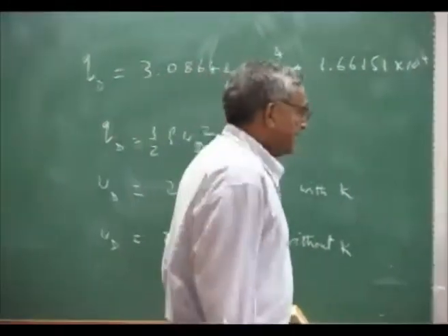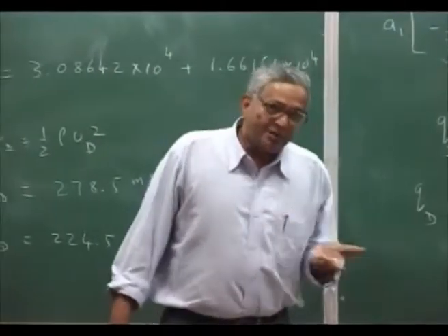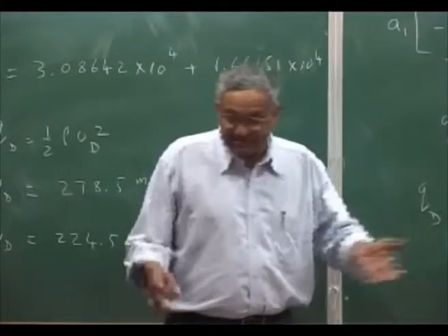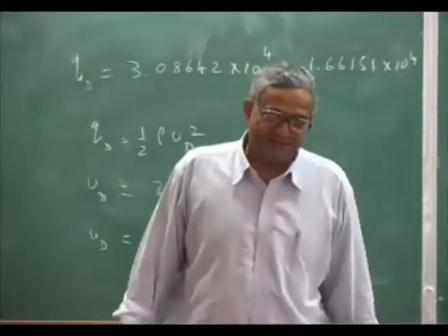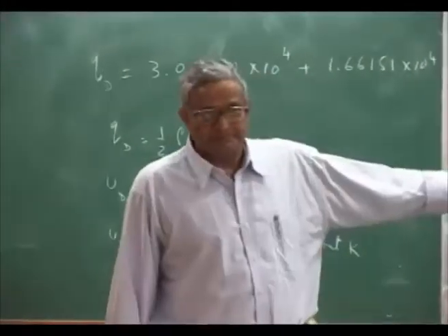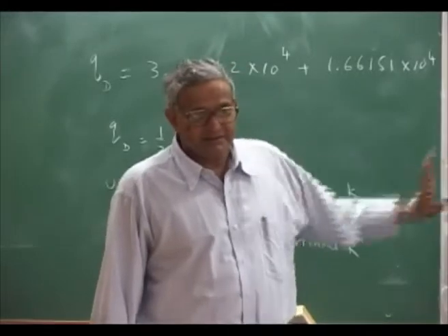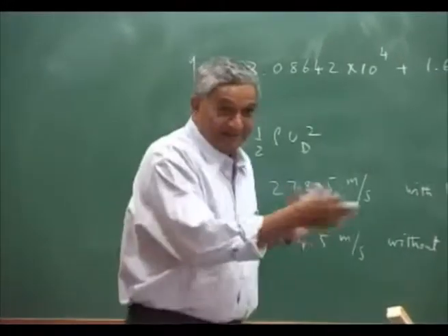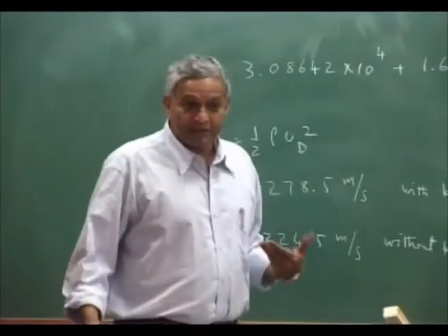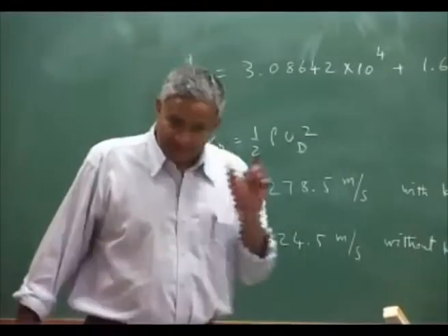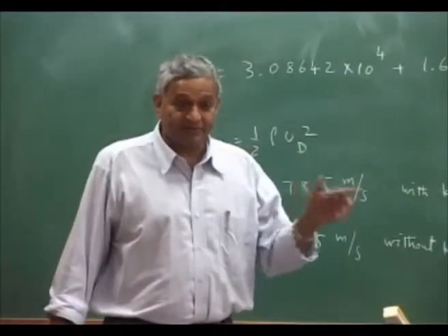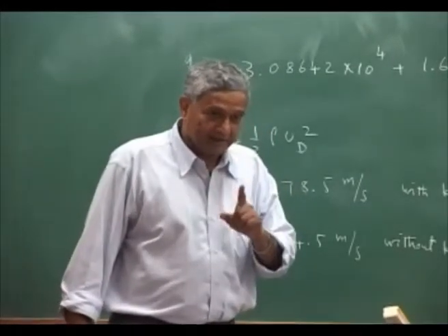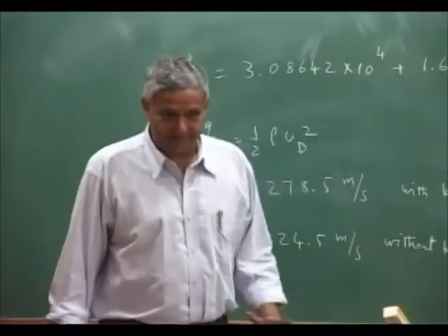This is where the entire problem is: what is the choice of the function which satisfies my boundary conditions. That is why I have given you the boundary condition and you are able to evaluate all these things. If your function is not given, then you have to go and identify that function which satisfies that. So this is the problem in using the Galerkin method. Please understand.